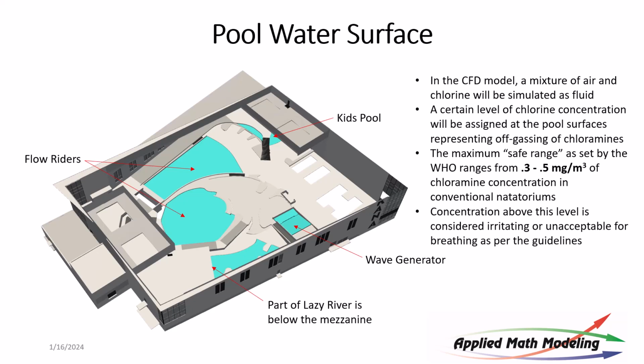If it gets into the breathing zone of humans in this indoor water park, they're going to both smell it and feel it. In other words, it's something called swimmer's lung. When it gets into your lungs, it causes irritation. So the designers of this particular facility contracted us to perform analysis to determine whether or not there was going to be sufficient airflow, flushing of clean air into the environment to dilute the chloramine gas to a safe level.